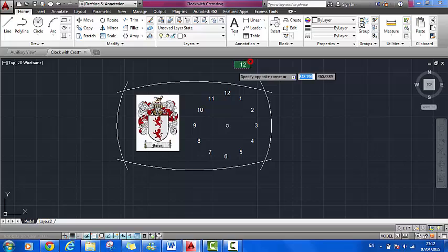Now, these lines here on the outside, on the actual project, these are going to serve as raster lines. They're going to show a student exactly where we need to cut to on our bandsaw and then sand to on our sander. They're not going to be cut out because it's going to be thick timber. Maximum thickness for our laser bed is around 10 to 15 millimeters thickness timber.